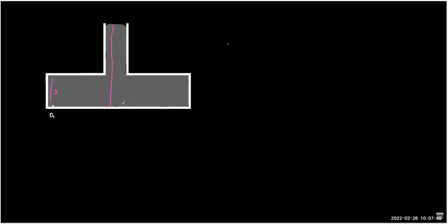So wherever the point may be, the pressure depends on how much the depth of the point is from the given free surface, the open surface, which can be anywhere. So this height will matter, not this height. If this is H dash and this is H, then definitely H will decide the net pressure at A, not the H dash.